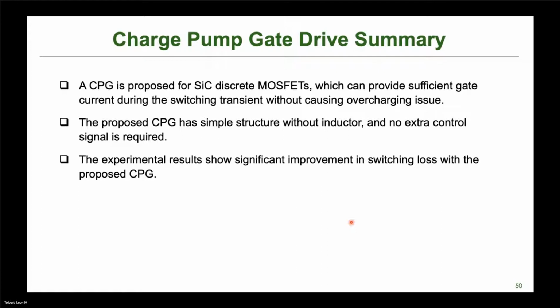That is correct. And I think a lot of what we've looked at was that, at least with silicon carbide and its unique characteristics, we could do hard switching to a large degree and not have to worry about all the additional complications that come about when you do soft switching. And so we've focused mostly on phase legs as well, because most of our applications have been inverters, looking at things like motor drives or just utility inverters connected to the grid and whatnot.